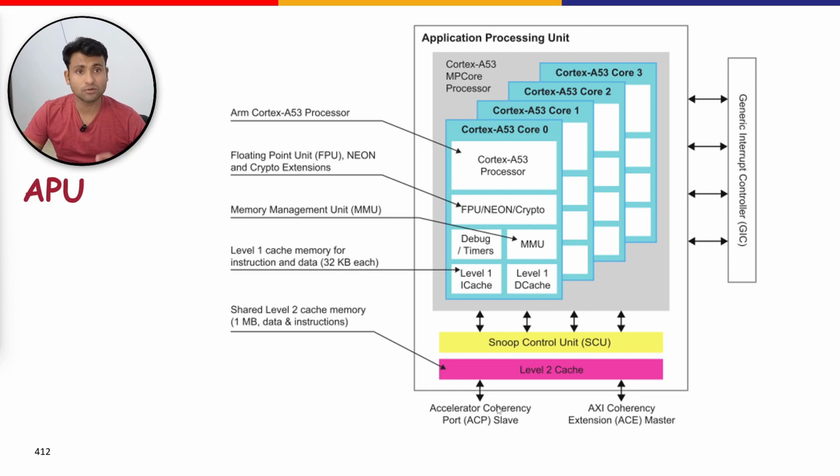As we had discussed about the cache coherency interconnect, the CCI within the Zynq MPSoC is connected to the APU's master bus interface using a 128-bit AXI coherency extension, which is known as the ACE port, AXI coherency extension master. This ACE protocol allows the APU's master interface to access the given address space and retrieve up to date data. The data may be copied locally to L1 cache or to the L2 cache memories to optimize processor performance.